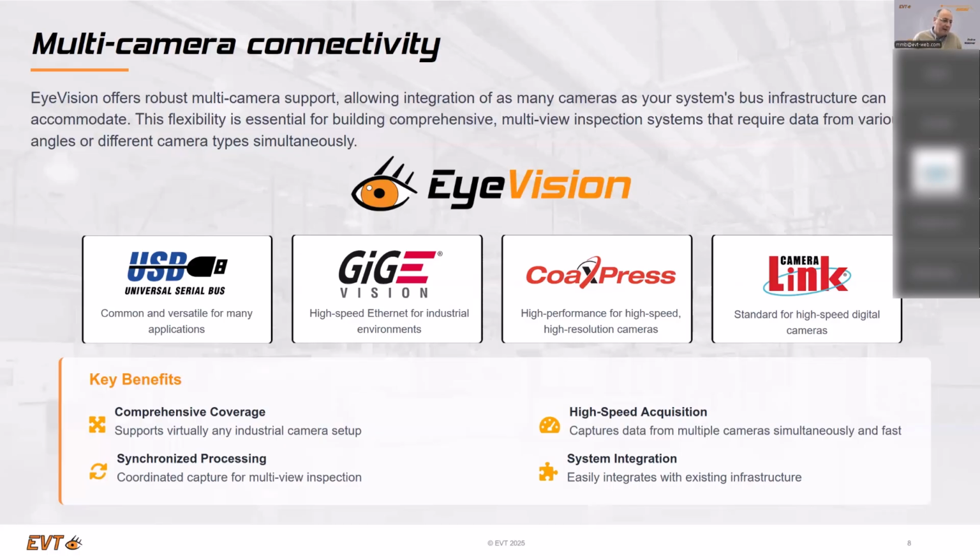If you have after the measurement part some additional things like finding scratches or finding dents or any other defects on the part, of course, you can use AI additionally. And finally, if you do this, the AI also gets the advantage of the good light because it works much better if the light situation is good than if it's not good. So the advantage of AI is it can also work if it's not so good. But if you want to have a reliable, really good result, light is always good.